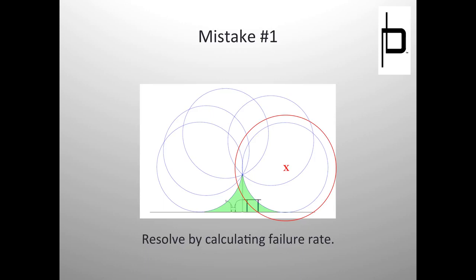So when you say 1 in 400 years or 1 in 500 years, what we're saying is the exposed area will get struck 1 in 400 years or 1 in 500 years. But the quote unquote protected area, we don't know how often that's going to get struck. According to this method, we're saying it's not going to get struck at all, but we know that's not true. It may have insulation failure, or for whatever reason, the step leader chooses to strike the equipment instead of the more attractive shielding electrode. Maybe you have bad grounding in the area, and that grounded shielding electrode is not that attractive. A number of different reasons. So when somebody says 1 every 100 years or 1 every 400 years, they're referring to only this exposed area.